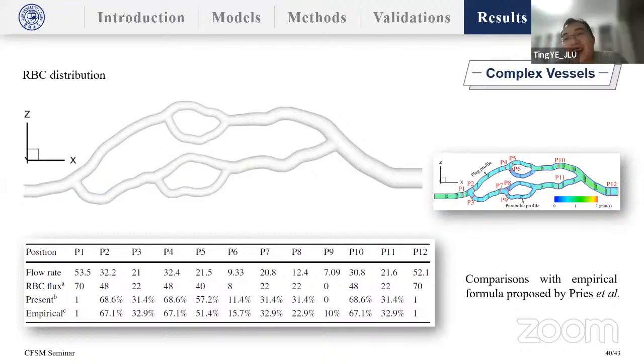But for SDPD, I use the equation of state P equals rho c squared. It's also for an ideal gas, right? But I get the result. We can find the theoretical and numerical results quite close.